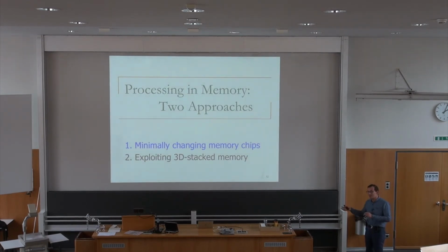So that has not been examined as much because people usually looked at, okay, we have this memory chip and we have this processor. How do we actually put the processor inside the memory chip? That's not an easy thing to do because if you really want to put a full-blown processor inside the memory chip, these two processes are very different in terms of manufacturing processes. Memory chip is customized for DRAM, capacitor, and in the processor chip you want actually high performance.